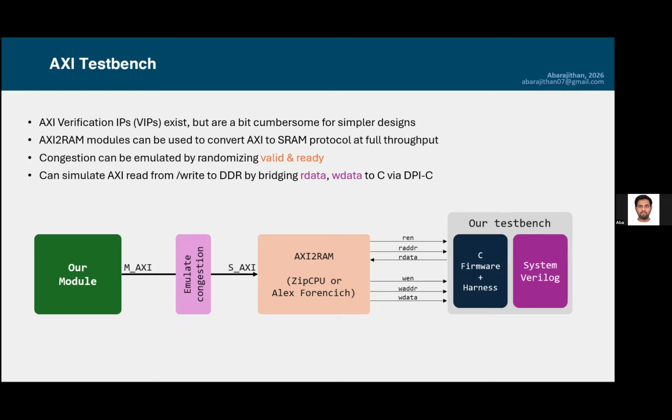Does our TB act as a CPU? So kind of yes. Basically the test bench will be running this C firmware. The way I do it is I want to test the firmware as it will run on the actual hardware, the way it will run on an FPGA or on your Ibex CPU or something. So the exact same code.